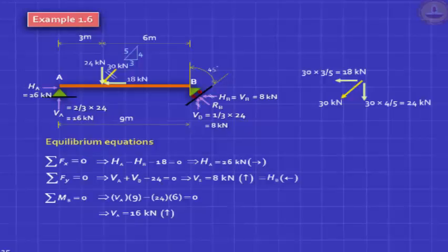See, now you have the confidence you can find support reactions in any problem if it's statically determinate. Whatever we did, you can write down in long form, and your resultant force is the resultant of this, which is square root of 8 and 8, which is 8 root 2, 11.3. If at all you need a calculator, it's here. But even if you write 8 root 2, you'll get full marks.